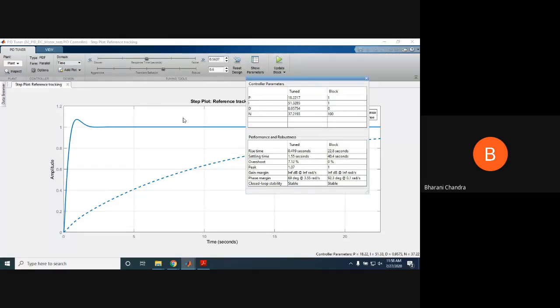However, this is the first such control design that the MATLAB auto tune will automatically tune. But one thing to observe here is that these tuned values are not the desired ones. Whatever you are getting, the rise time, settling time, and overshoot are not the desired ones, because the overshoot is very large. I want less than 5, and similarly I need the settling time faster.